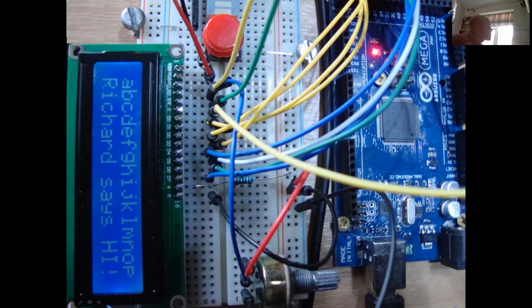And then the other ones, these other 3 on the end here, the enable, the read, write, and the other control line, are going off to port G. The wires are over there somewhere as well. And there's my variable resistor. And you see the middle of the variable resistor is going to the V0 pin. So I can turn this dial here. I've got the ends of it. One is going to the 5 volt. One is going to the 0 volts.